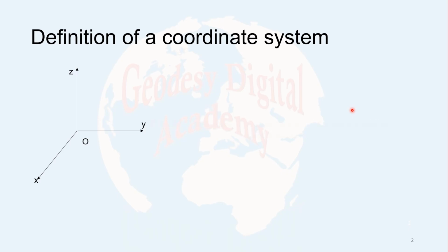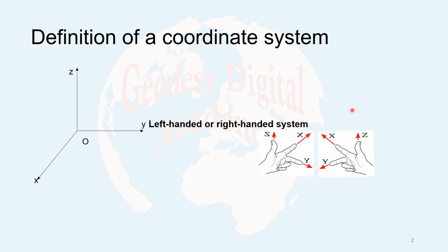And the last point, the direction of the y-axis, is defined based on the type of the system: if the system is left-handed or right-handed. What does it mean when I say right-handed? In a right-hand system, if I have this thumb along the z-axis of the system and the index finger towards the x-axis of the system, and I can complete a coordinate system by the middle finger like that with my right hand, then the system is called right-handed. And if I can complete the coordinate system by my left hand fingers, then I have a left-handed coordinate system.